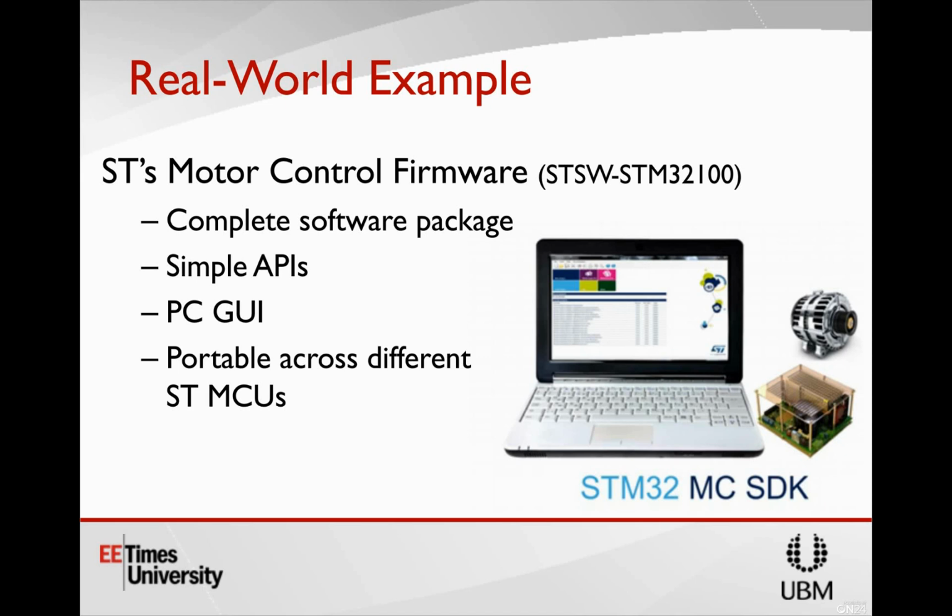Your speed controller is going to ramp up the torque that it's demanding. As soon as it does that, your current controller is going to say, well, I need more. I am not applying enough torque to the motor. My speed controller is demanding more torque, so let me apply more voltage in order to produce more torque.